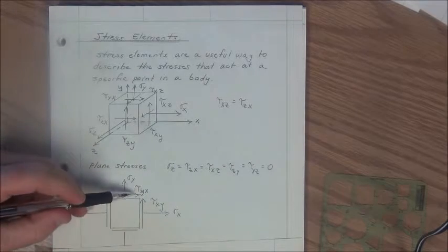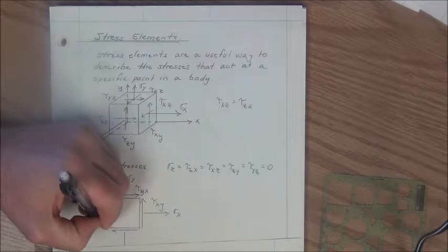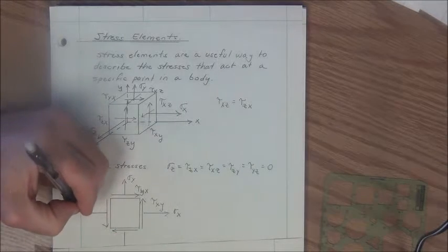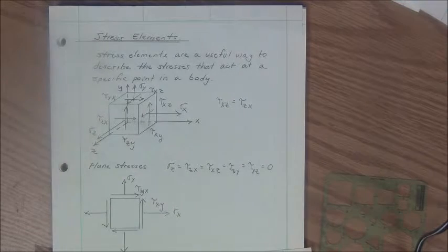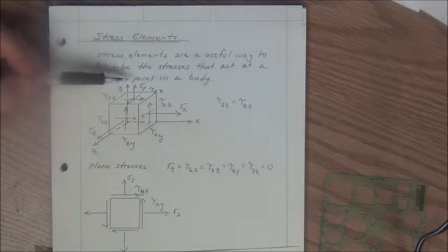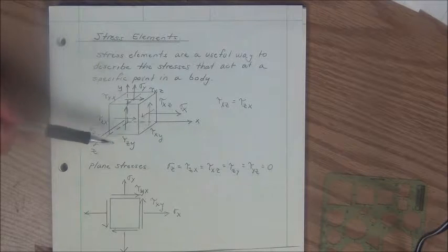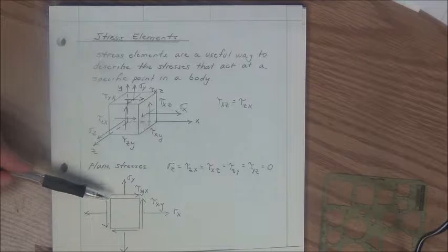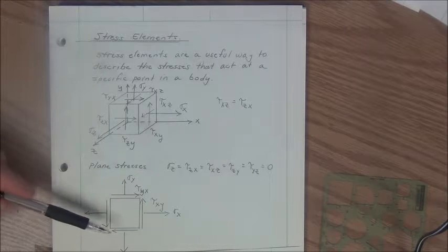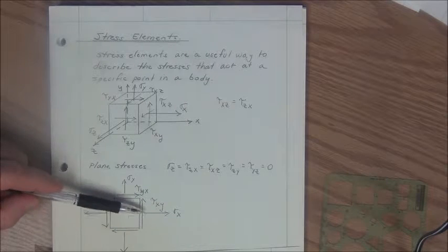And once we draw these stresses in these directions, we know these shear stresses must act to keep the system in equilibrium. And we have now taken this three-dimensional stress element that is relatively complicated to a simple plane stress element where the full element consists of two normal stresses and essentially one shear stress.